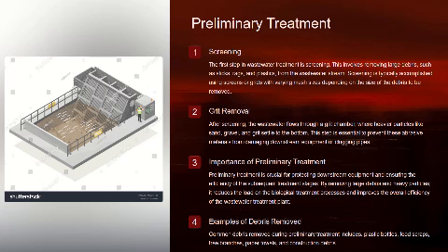So there are two important things you need to note about this stage. The first one has to do with screening, and this basically has to do with removing the huge impurities that are in the water. So things like rocks, sticks, plastics, the obvious things that you can really see with your eyes when you look at the water. You want to remove all of those things. The second thing is grit removal.